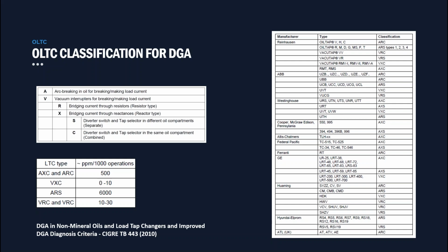Okay, and Sherwin has asked, is it advisable to conduct a DGA analysis for transformers not in operation for a long period of time, and are the DGA results still valid? If the transformer's offline, then gas generation levels shouldn't increase.